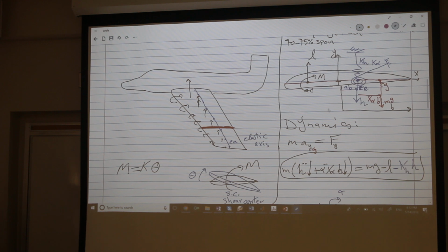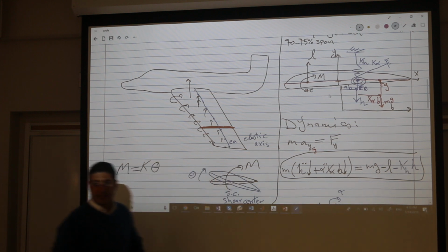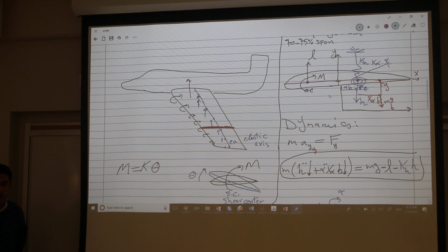Any other loads that create a moment at the blue point? The bending moment, right? The drag, I mean, we assume that the drag is collinear with that point, so it's not. If you want to do a more intricate analysis, you can account for it. No. At a particular section, the bending moment will not show up, because the bending moment is about this axis. It doesn't show up here. The twisting moment shows up here, and this is why we account for it.